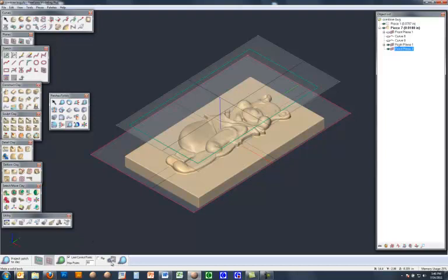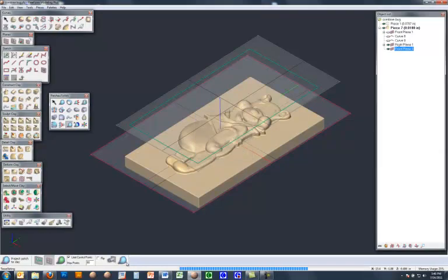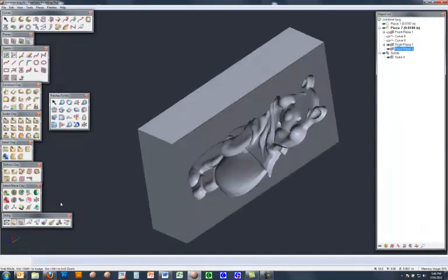and then in the end here, instead of hitting the surface option, the open patch option, I'm going to hit the solid command. And again, FreeForm goes away and calculates the surfaces. But this time, instead of leaving an open surface, it's going to leave me with a closed solid.